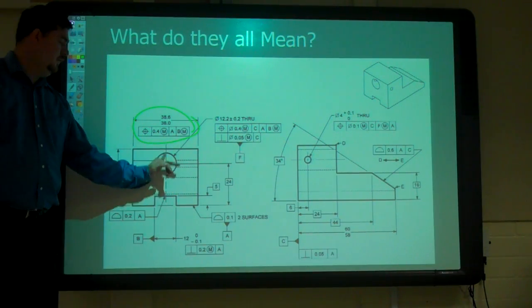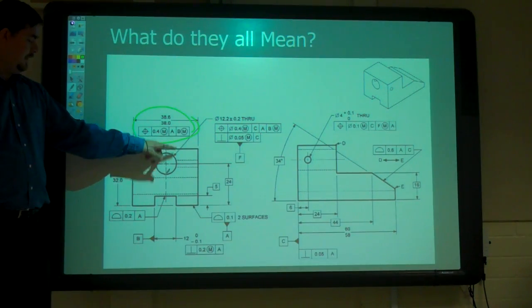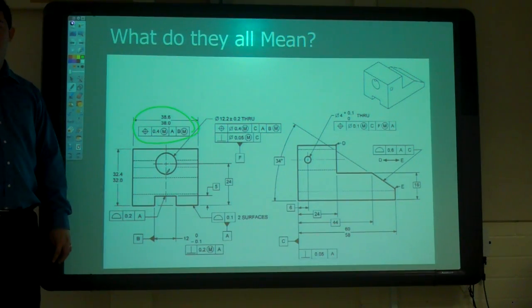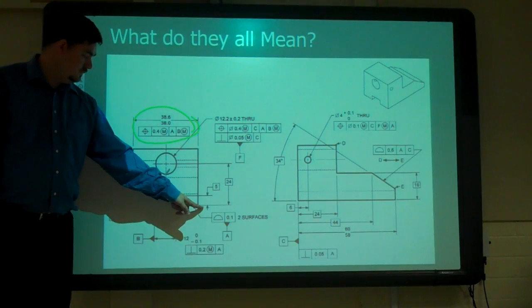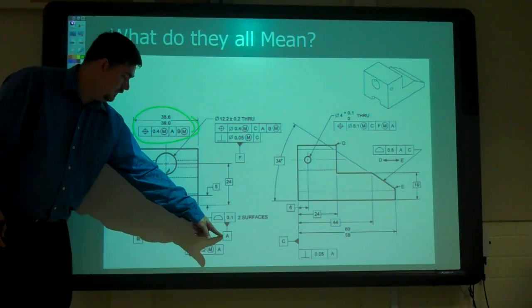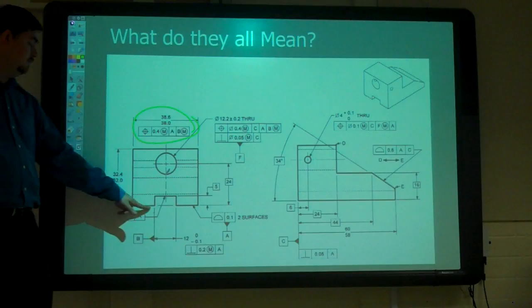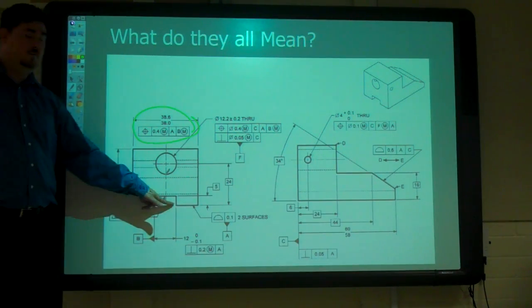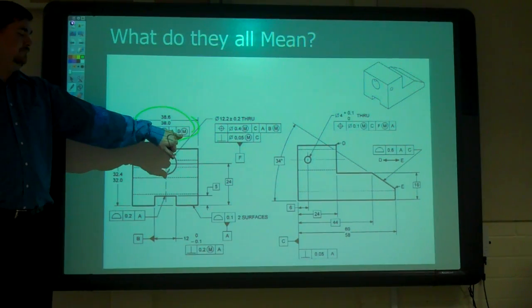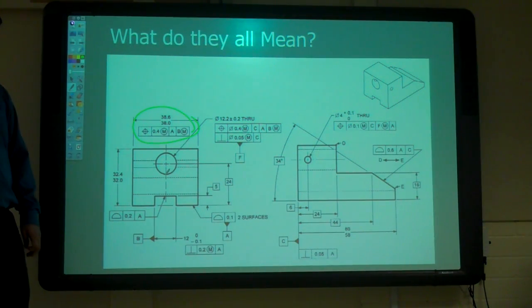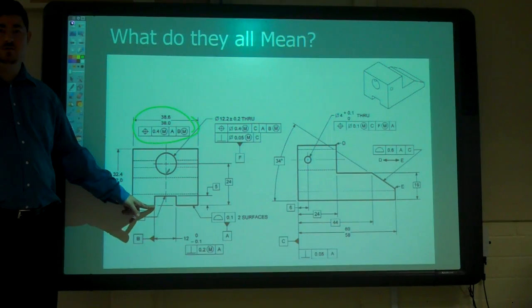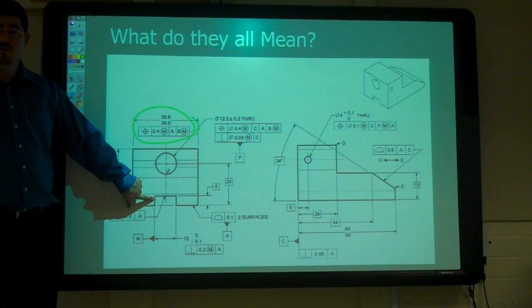So the center line of the part has to be in position relative to datum A, which is where? Datum A is right down there, those two surfaces, bottom part. Datum A is this bottom two surfaces, right? So relative to datum A and datum B, which is what? B is the cutout part. What about the cutout? Where is it? Is datum B this side? No, it's the left side. Well, actually, it'd be the same, it wouldn't matter, right? Either parallel.